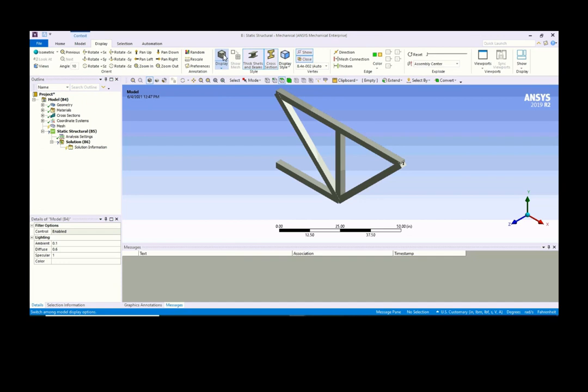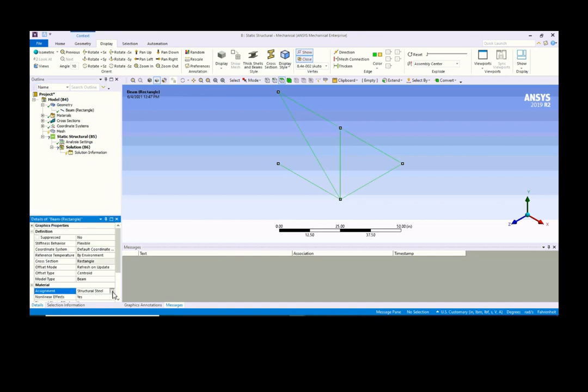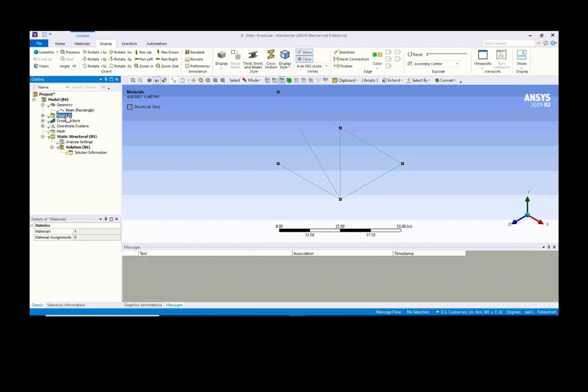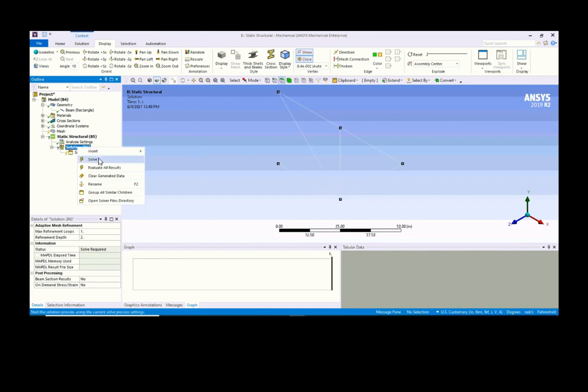So what we need to do is repeat what I have shown you just now. Here, for material, just now I didn't add it, you have to change to the correct materials. Then the mesh, then the inserts, the supports, as well as the force. Then you can solve it, or you can insert some post-process results before you solve it. So that is how you model these particular models using SpaceClaim.